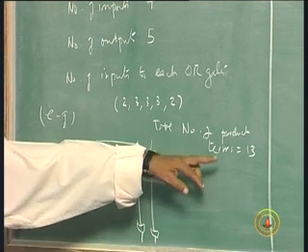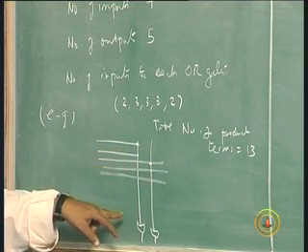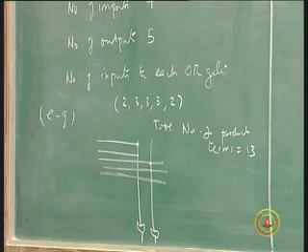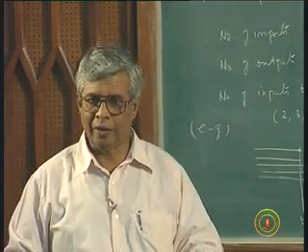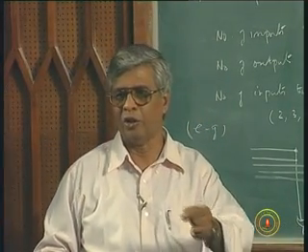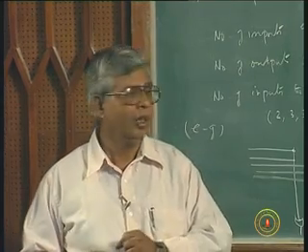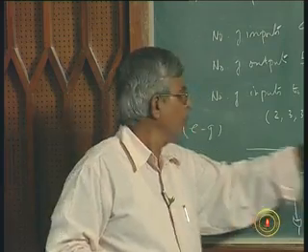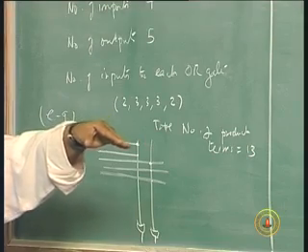There is no use giving this unless you know this structure, that is what I am saying. No use telling you that I have 4 inputs, 5 outputs and 13 product terms, you just minimize it, use it to get an implementation. Next question you will ask me is, how are these 13 product terms connected to the different OR gates? If I do not tell you that, there is no way you can change those connections, whereas in a PLA this is enough. So, I can reuse them in different OR gates, right.